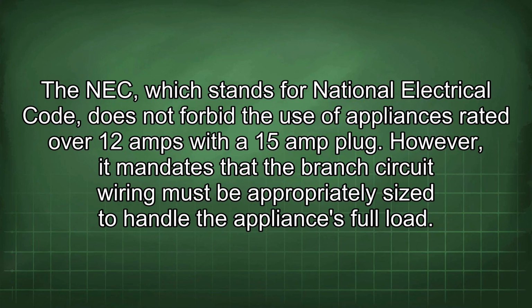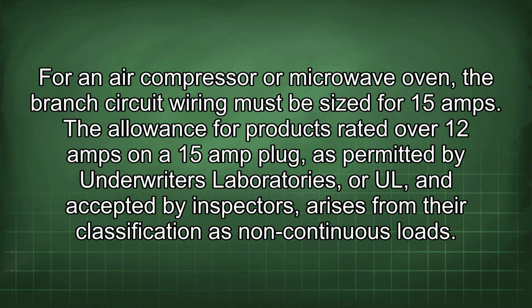The NEC, which stands for National Electrical Code, does not forbid the use of appliances rated over 12 amps with a 15 amp plug. However, it mandates that the branch circuit wiring must be appropriately sized to handle the appliance's full load. For an air compressor or microwave oven, the branch circuit wiring must be sized for 15 amps.